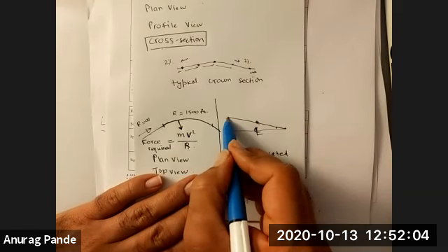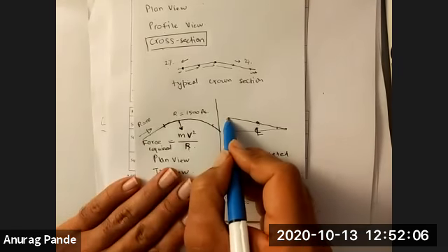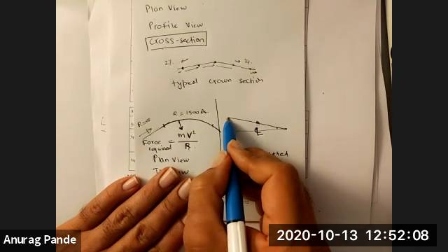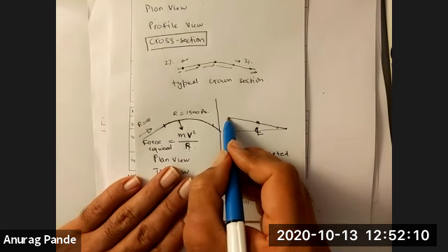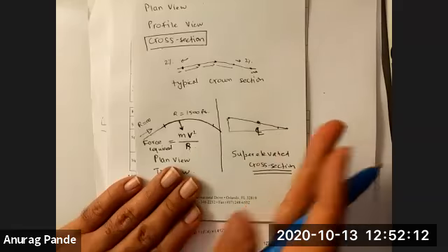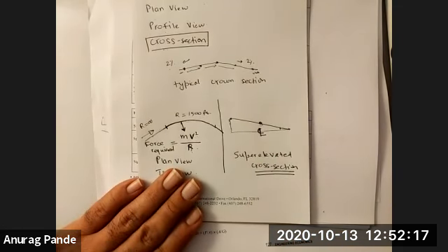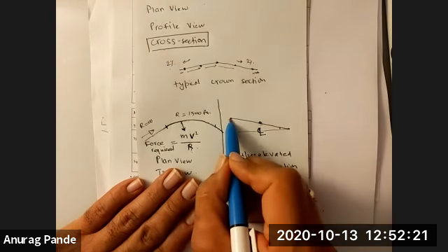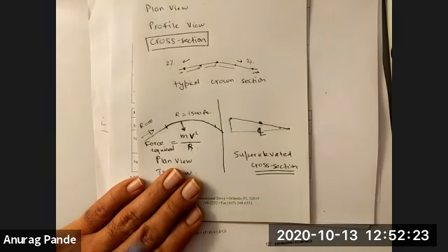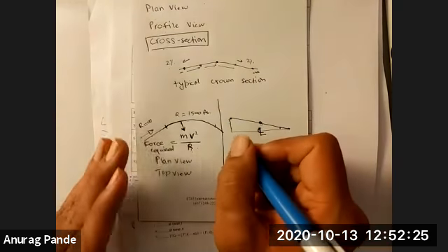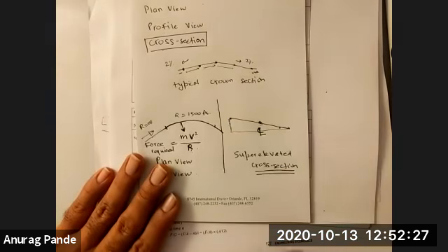Obviously, the roads that Caltrans or the state highway agencies would design will have no cross-section slope that looks like the NASCAR road. But that will help you visualize what kind of super elevation we are talking about. Typically on public roads, the super elevation could be as high as about 8% on rural roads because the speeds are higher.